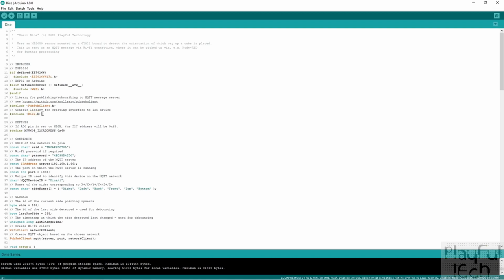So this could be really useful. For example, let's say you get hold of some sort of sensor that doesn't have a library pre-written to access it at all. So long as you've got the datasheet for the sensor in question, you can actually write your own functions against it to control it, to set values, to read sensor values as well. So I kind of thought that would be a useful exercise to show you how to do that. That's what we're going to be doing in this project. So I'm only including the generic I2C library itself. There's nothing specific here about the sensor board we're using.